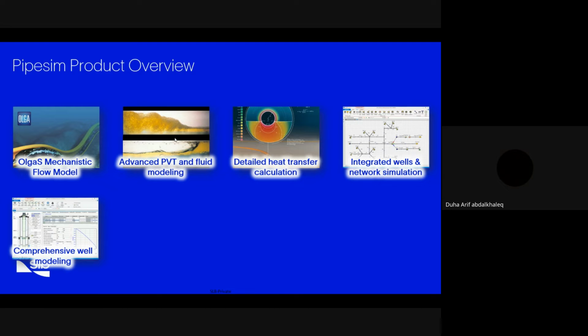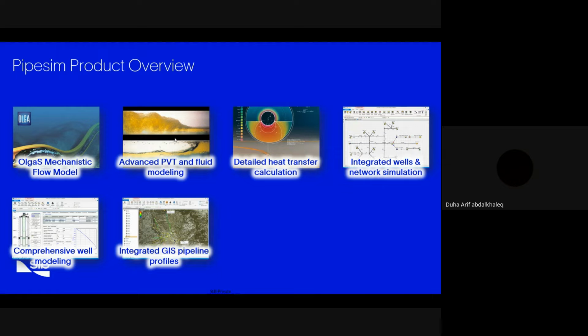So when it comes to wells, Pipesim has comprehensive well modeling where we can model the well from A to Z. We can model the fluid, the completion, the casing, tubing, and all the downhole equipment inside the wells, such as packer, sliding sleeve, etc. Also, Pipesim has an integrated GIS pipeline profile, which utilizes GIS, a geographic information system, to automatically build the pipeline networks and automatically capture pipeline elevations.